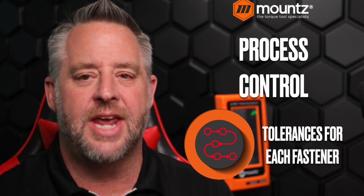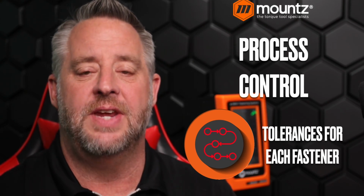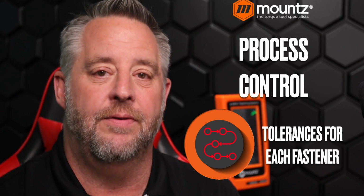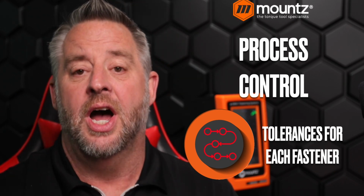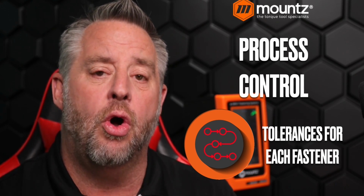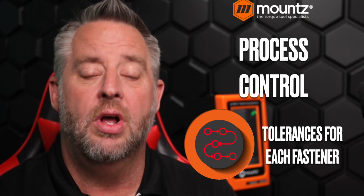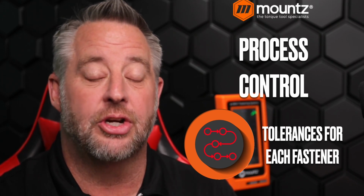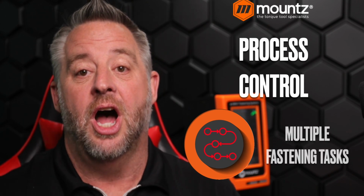And those tolerances can be based off of either the torque value, it could be the amount of angle that is run, it could be a number of different factors that we can control with the tool that allow us to be able to implement that in the process control during the fastening rundown.